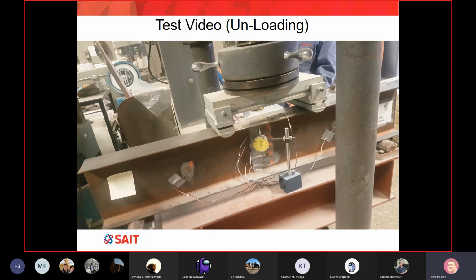As long as we are within the elastic limit, if you remember what the elastic limit means under tension and compression, there is one point called the yield point. If we pass this point, we get permanent deformation, so our beam will never go back to its original shape.